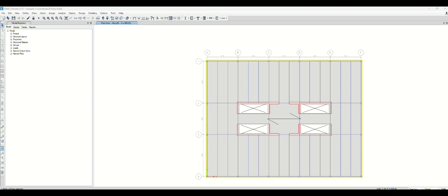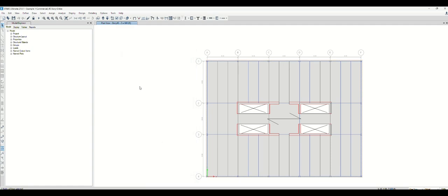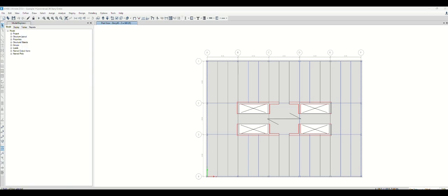And in this model, I have a construction dialog, which I'm not going to use for column and beam design. This is only for composite floor framing beam design. So most likely we're going to use dead load, which is self-weight, and superimposed dead load and live load, right? So similar to, excuse me, the composite floor framing design, we're going to set up the load combination for